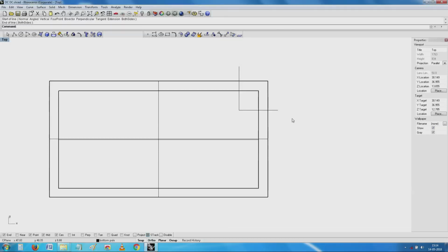See, that much of a notch I need to give, so that the heat sink does not short. So, I will now copy this, like before, I mirror this, and at this point the easiest for me now is take this, again take these 2, mirror it again. See here, I am getting better at it. I will now go here and try to cut these surfaces completely.